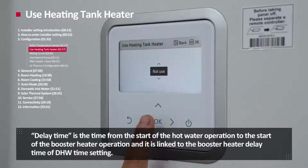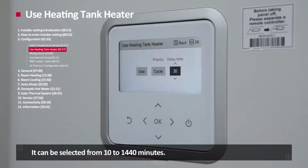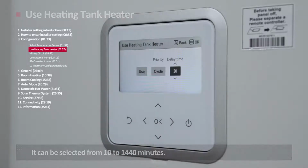Delay time is the time from the start of the hot water operation to the start of the booster heater operation, and it is linked to the booster heater delay time of the HW time setting. It can be selected from 10 to 1440 minutes.